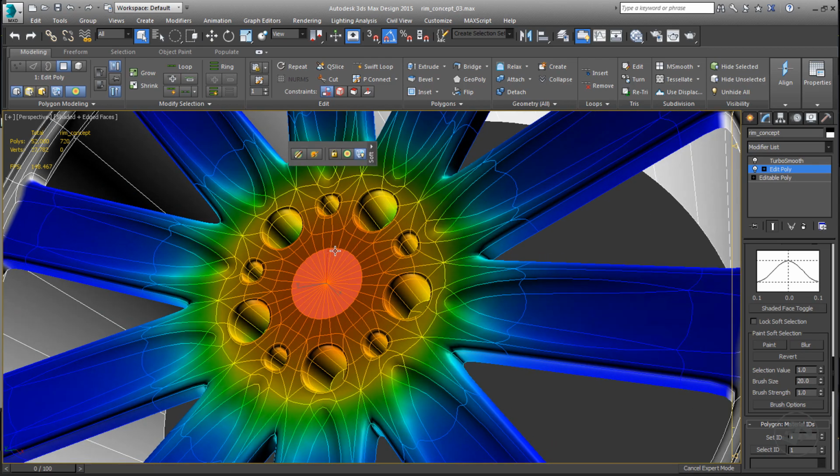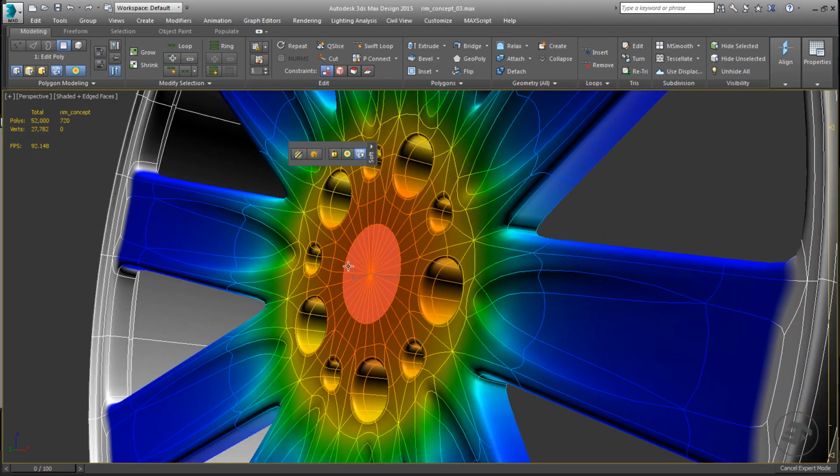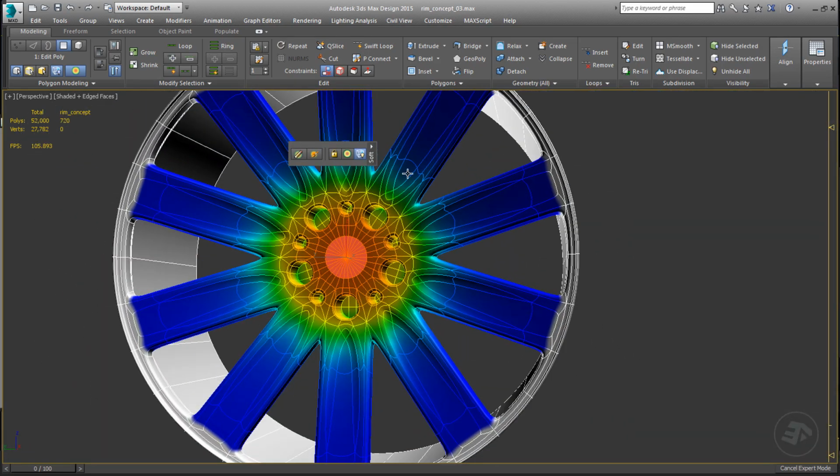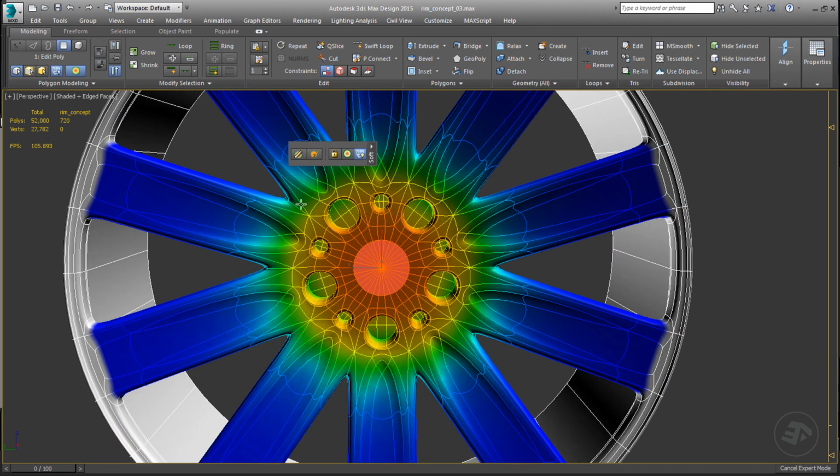The areas in gray are frozen and will not be affected by the soft selection. The areas in dark blue color are the limit of the soft selection effect. They will be subjected to the lowest effect by the soft selection. As we move closer towards the center, you can see the color switches to hot colors until it reaches orange, which represents the areas that will be affected the most. They also represent the center of the fallout.